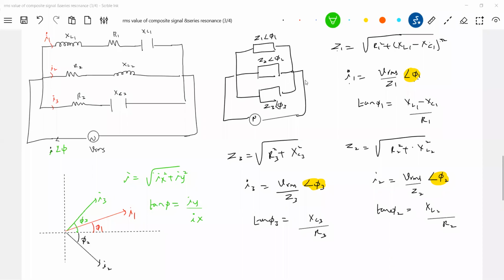It's not a series circuit, it's a parallel circuit. VRMS, RC circuit. Across the RC branch, the current will lead the applied voltage, no? So I think what I did, I2, I3, symbols. Correct, no? This is I2. It's a parallel circuit, not a series circuit. An RC circuit is a lead circuit. Current leads the applied voltage. In an RL circuit, current lags the applied voltage. You have to be very careful in determining those phase angles.